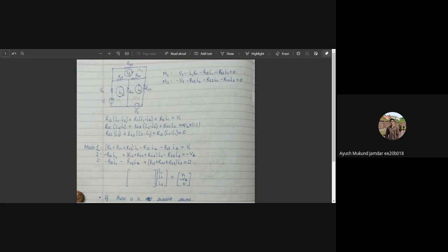And this is a resistance matrix. So when we take the inverse of the resistance matrix and multiply on both sides, we'll get the currents directly, I1, I2 and I3. And once we get the currents, we can find the current and voltage across any branch, any node on this circuit. So that's how it works.